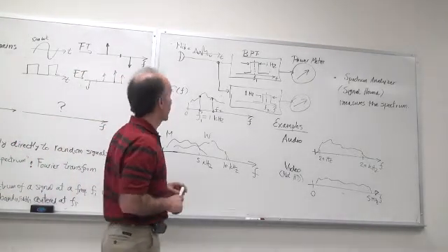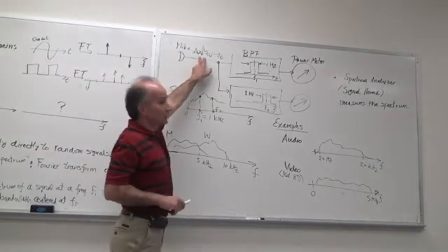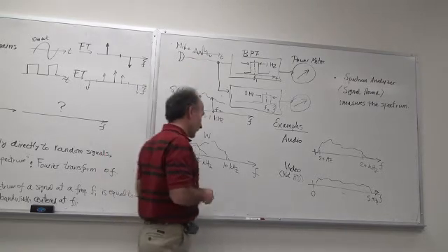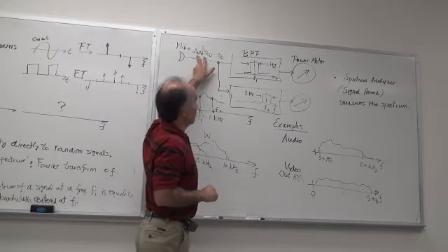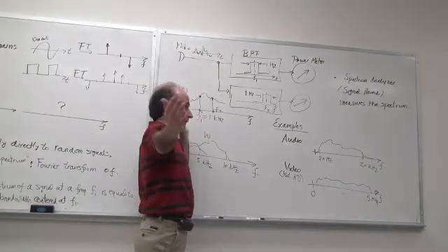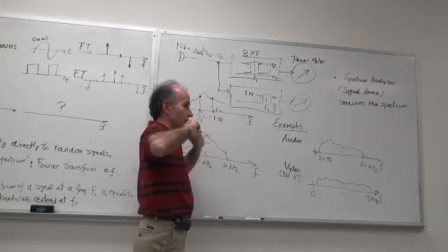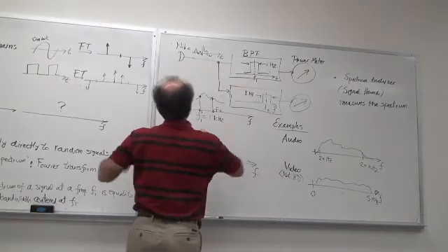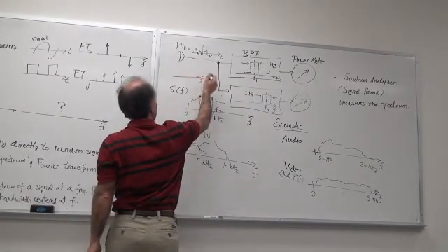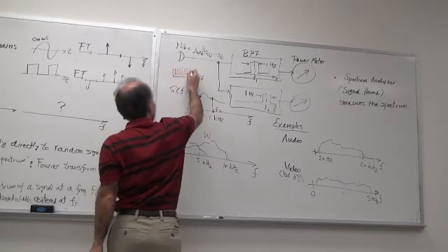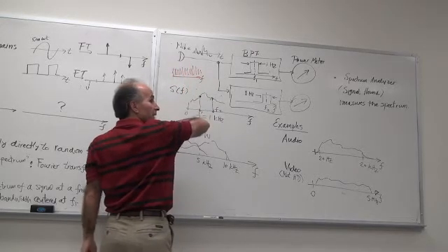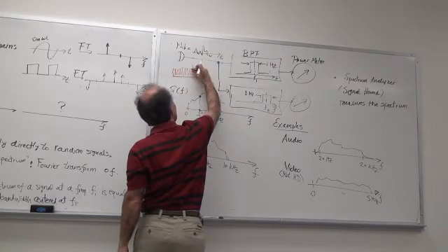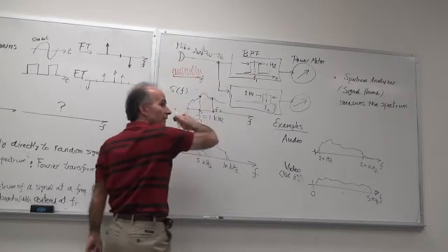The FFT, okay, so if you take this microphone signal and take the FFT of it, that's not the spectrum. What happens, if you're curious, is that if you keep taking the FFT of a signal directly, regardless of how long that FFT is, the spectrum does not converge, meaning it does not approach its final value. If you take the FFT of this random signal, this is what you will see. As a function of frequency, you'll see jumps up and down. It has a huge amount of noise on it. And regardless of how long you make this, and you take the FFT for longer and longer, this does not converge. This deviation doesn't go away.